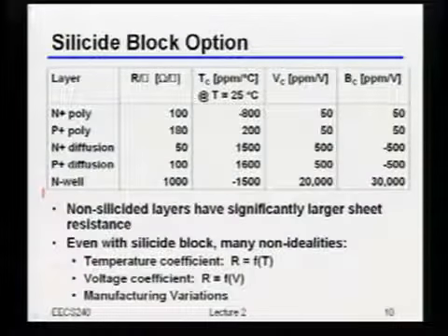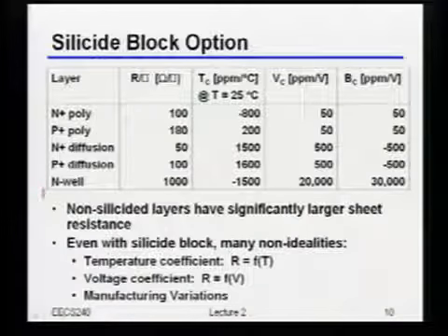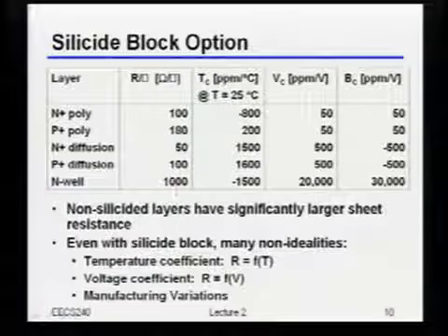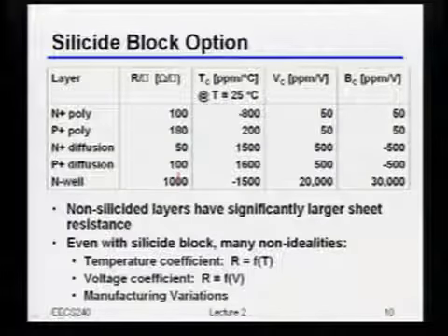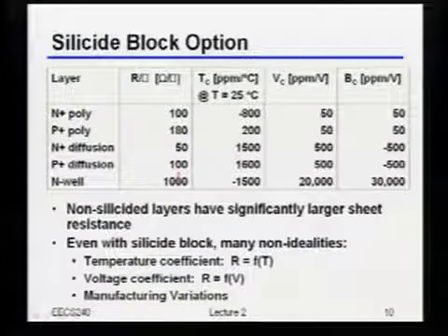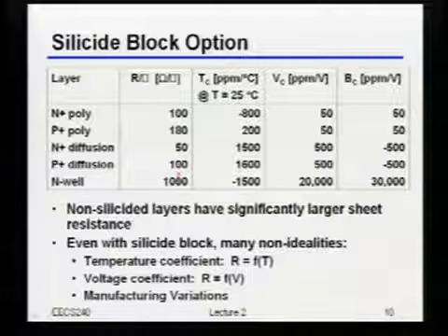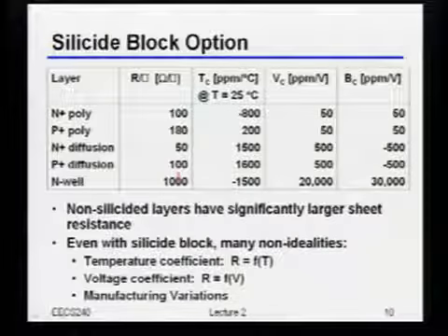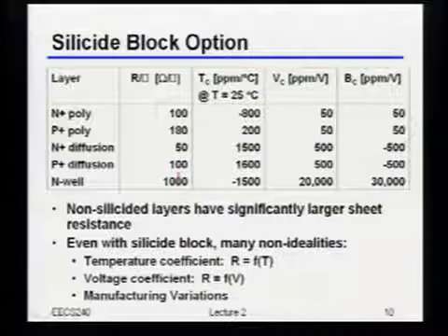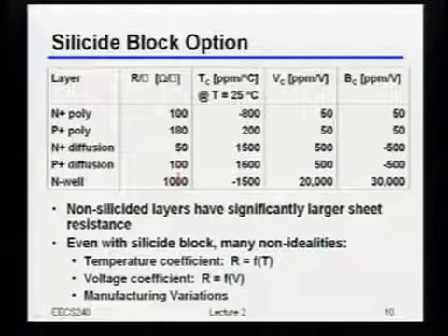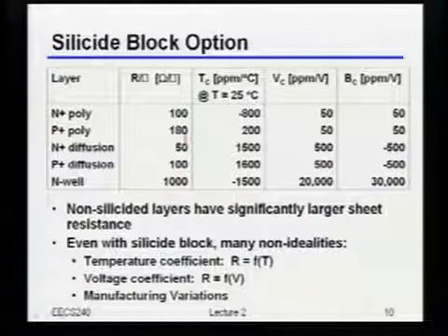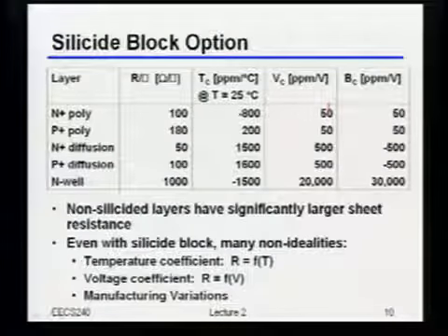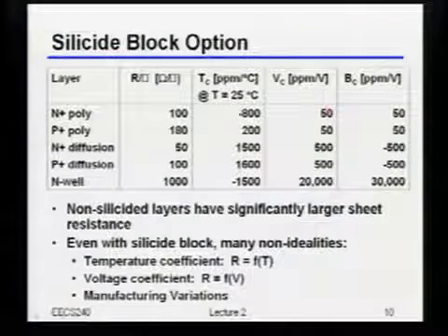In fact, sometimes they'll just give you poly resistors that have been specifically lightly doped to get you higher resistance, and then you can get back up to close to a kilo ohm per square kind of number. Okay? So that's good news, so we can get more reasonable things that maybe will have lower capacitance. But unfortunately, a lot of the issues that we talked about still aren't going to go away. Okay? So all of these things are still going to be voltage dependent. In other words, they're going to be somewhat nonlinear. And actually, I'll talk about this in a second.